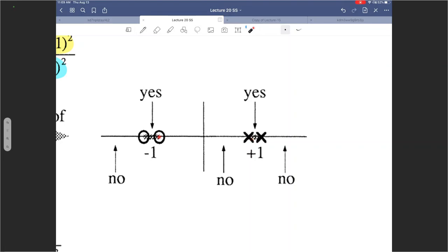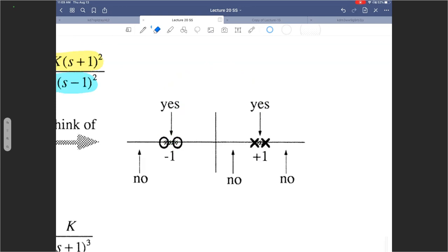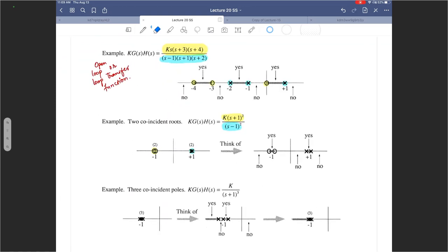So my guess for the root locus here is it starts here, it breaks away, comes back here, and then ends at the zeros here, right? More about this later on. But I hope you see with this that as you combine the rules of sketching the root locus, you will be able to piece this puzzle together.